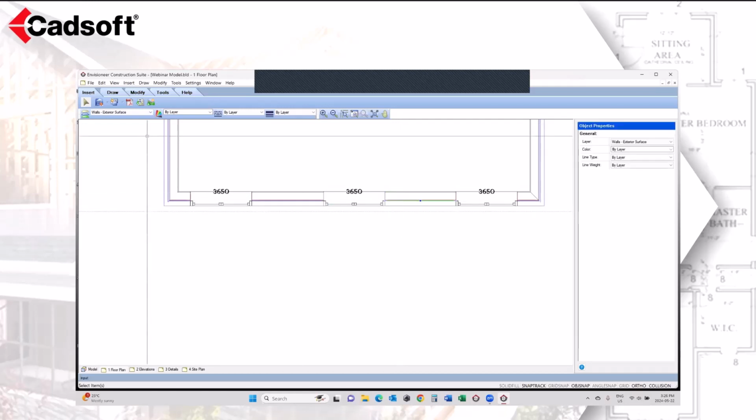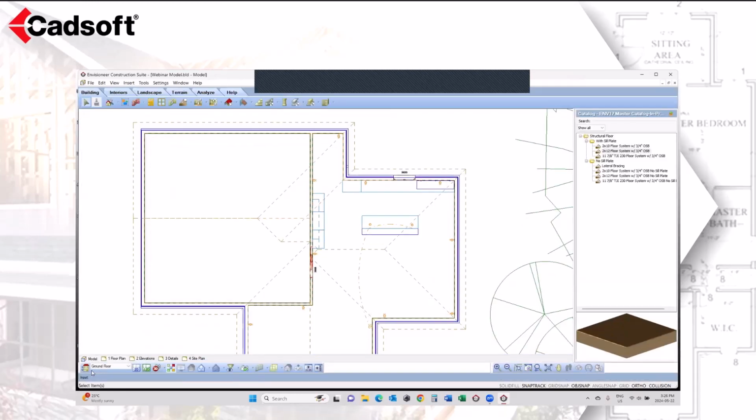And because it has them all on each individual layer, when it brings out all of those 2D lines that you can print, it means you can have different wall line definition to each line. So on the exterior, if you wanted this to be a very light line, but you wanted your stud lines to be a heavier line weight, you can do that.